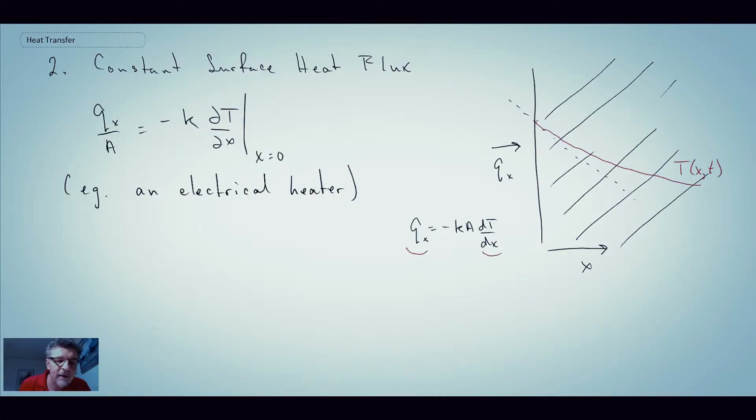So that is constant heat flux, and there is another form of constant heat flux surface, that of no heat flux. Let's call this A, sorry, I should have put an A. This is finite heat flux. And we can have B, which would be an adiabatic or insulated surface, or no heat flux.